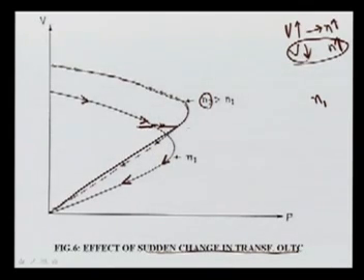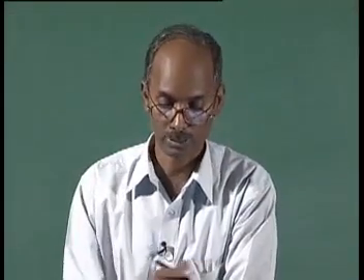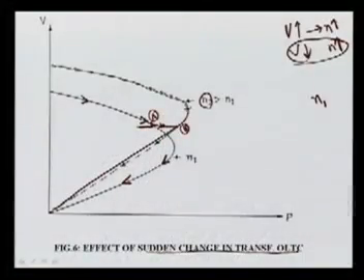What it shows is that after changing from here to here, point A was stable, but now it is going to point B, which is unstable in the sense of voltage stability. Why? It is less than the nose point and is below this. So this portion from here to here is the unstable zone, and only this upper portion is your stable case. So a sudden change is also very dangerous and it may lead to your unstable